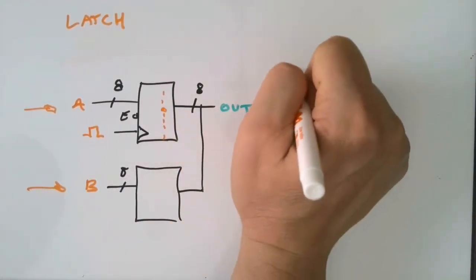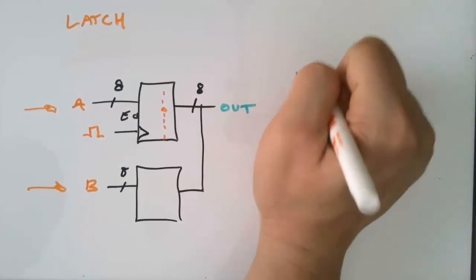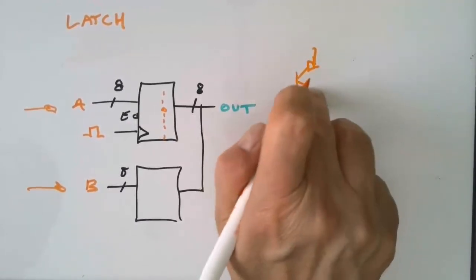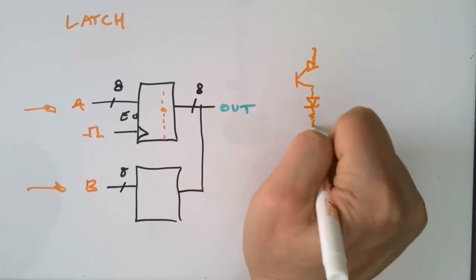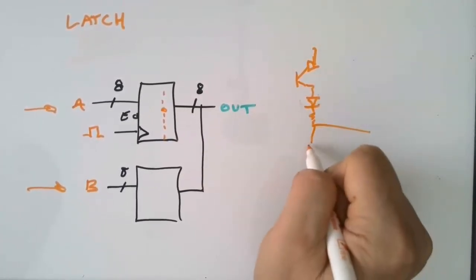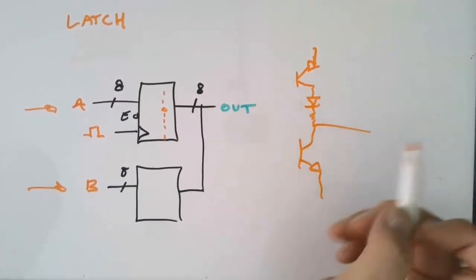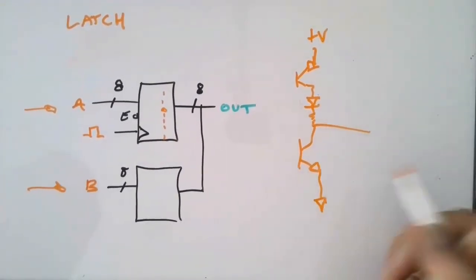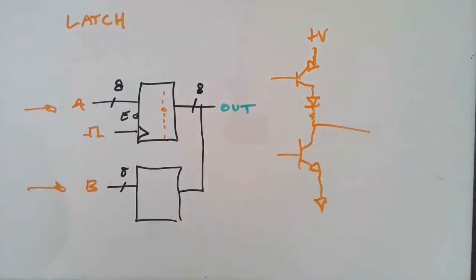talked about this kind of totem pole output on our gates. Usually we have a PNP transistor on the top of an output, going typically to a diode and a resistor and then an output pin. And then we go to another transistor that's connected to ground like that. And this side is connected to plus voltage, and this is ground.